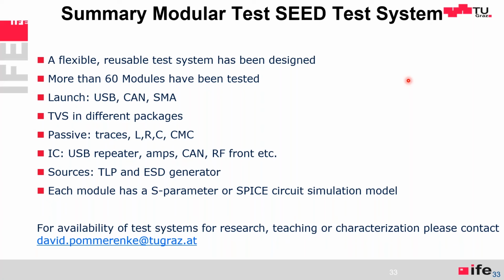This is basically to create models and to verify models against simulation, because we're coming to the point where ESD protection cannot be designed by datasheet anymore. On really high speed I/O, one has to use other methods to design, and one has to refer back to simulation. And simulation is only good if one has models, and obtaining the models is a non-trivial task. And of course, the manufacturers are asked also to help to create the models. This is the point where I want to finish my talk, and I'm open to questions.